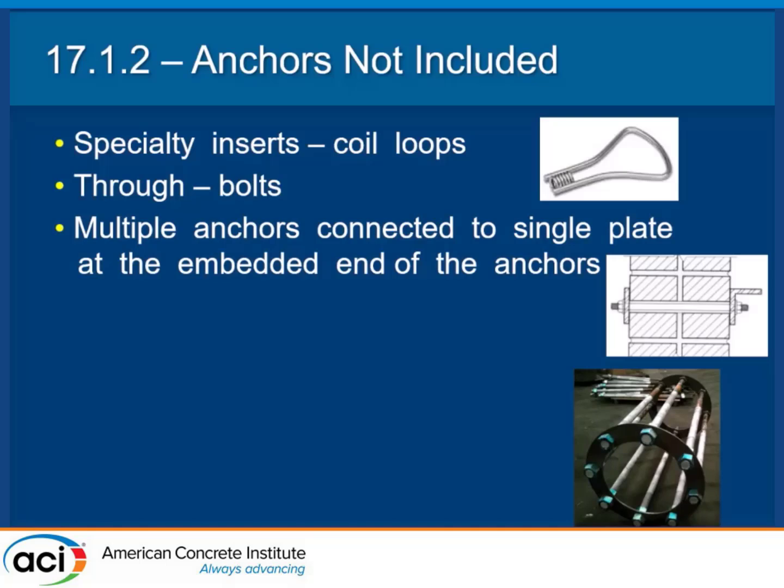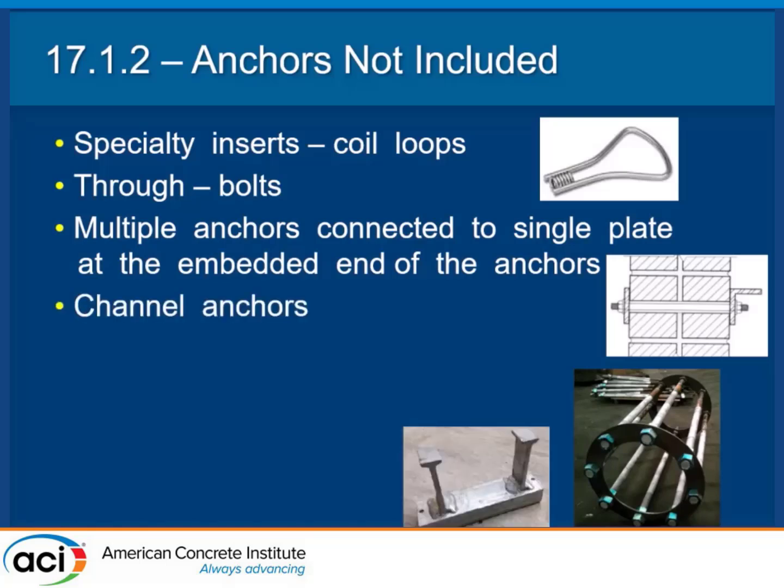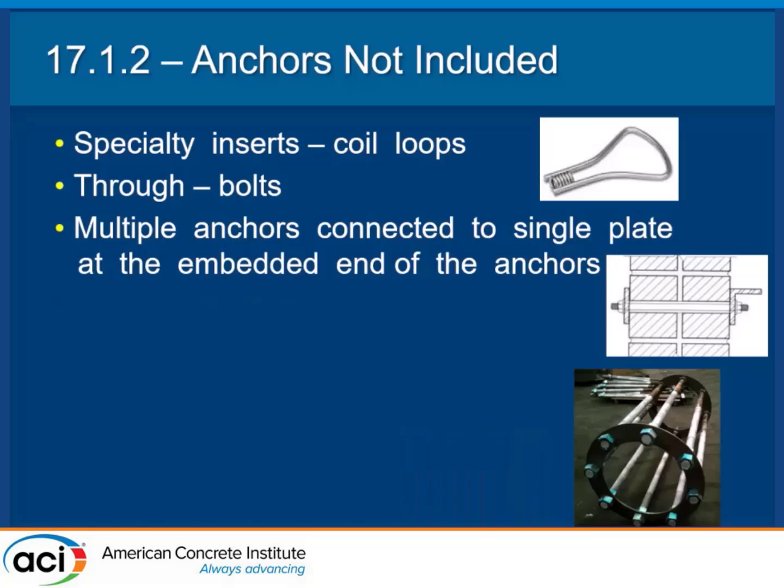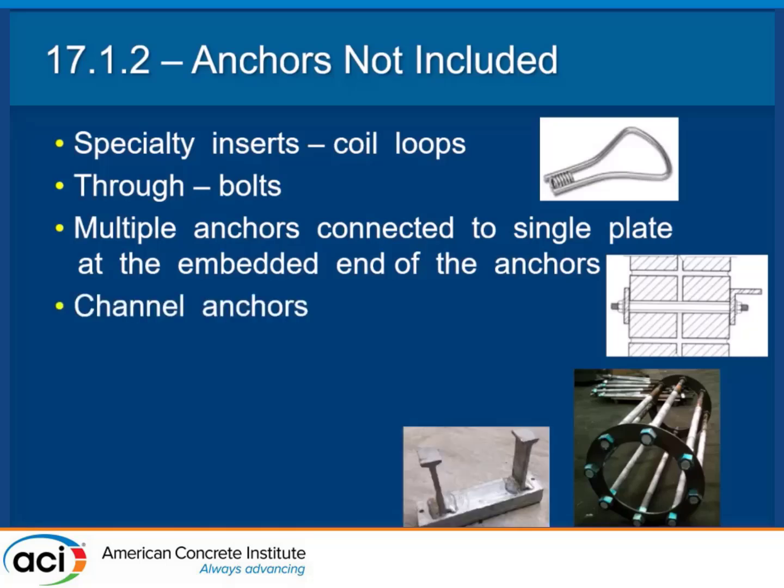Sometimes you'll see this in very popular and more industrial jobs. You'll see here at the bottom, you'll have anchors that they set out of the top, and they come down to some sort of plate. In this case, it's a circular plate, and they're using all those anchors attaching that plate, and they're wanting that plate to expand the bottom, for your breakout, to increase the breakout angle. Well, it doesn't change the angle, but instead of the breakout starting at the nut, it'll start all around that perimeter. Now, we don't really have any direction on that. There are lots of papers out there that you can go find, but we're kind of on your own.